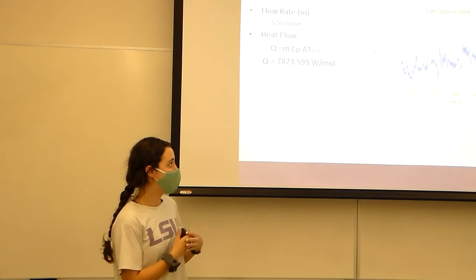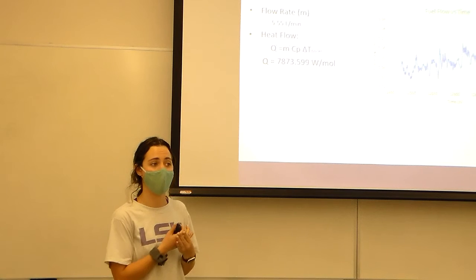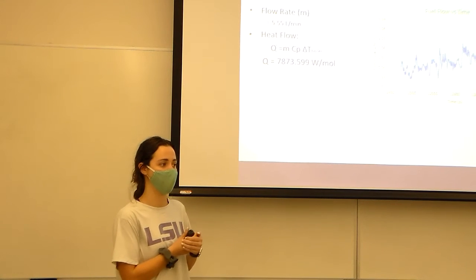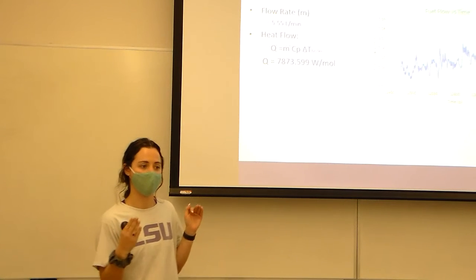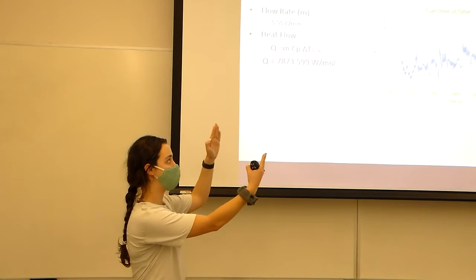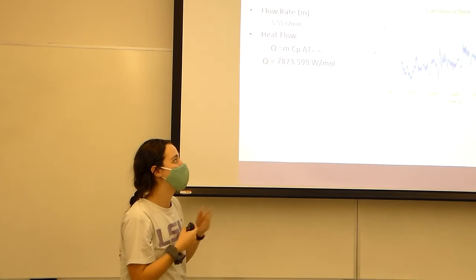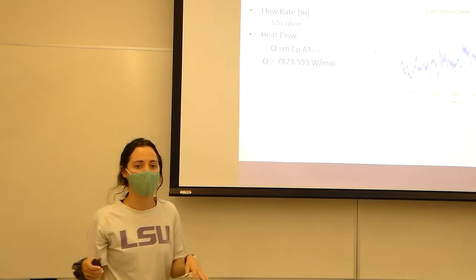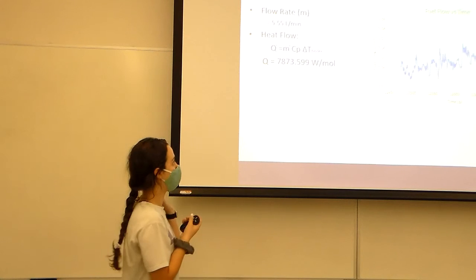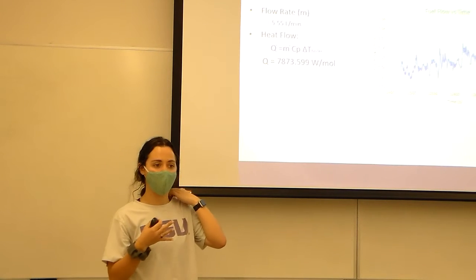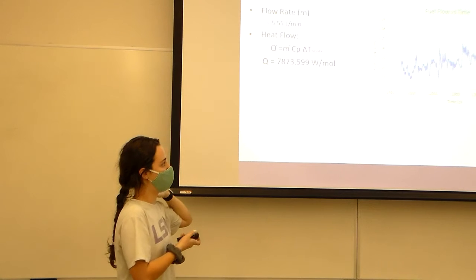And then for the flow rate, as you can see from this flow rate graph, there was no consistent flow rate at all. This was the same time window; I tried to stay consistent with the time in seconds that we used. During that time, the flow rate is all over the place. I took an average to find where our steady state would be, which is about 5.5 liters per minute, which is very, very low for a Rankine cycle.